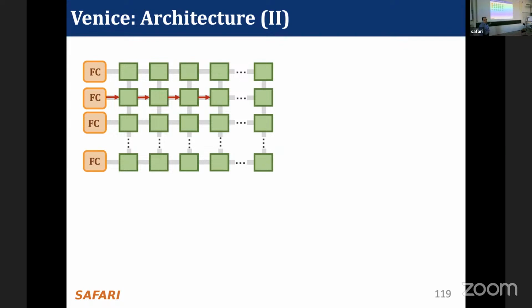I mean, here it is available, but imagine that it's not available. So we need to take a non-minimal path, and then we reserve the non-minimal link that we take. Again, here also we do that routing function again and again. And at some point, the scout packet cannot reach the destination, and it gets misrouted and goes back to the previous router, and we need to release what we have reserved before. It's actually a little bit complicated, but it works.